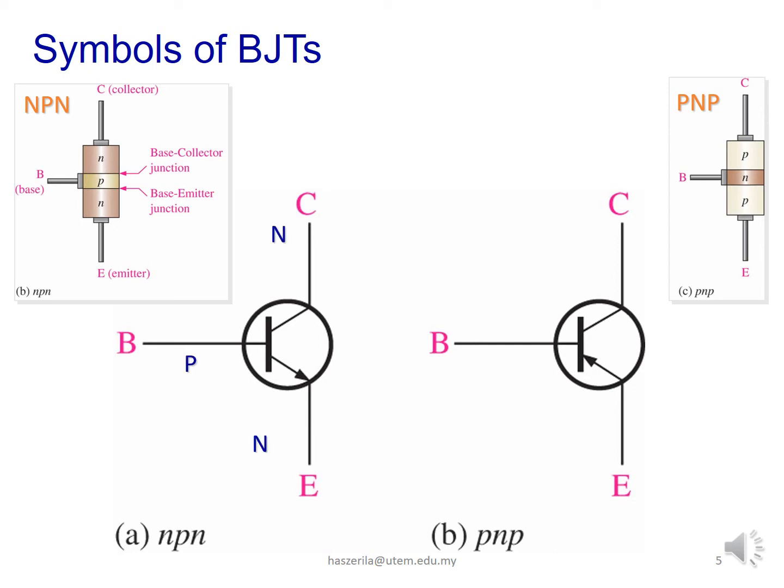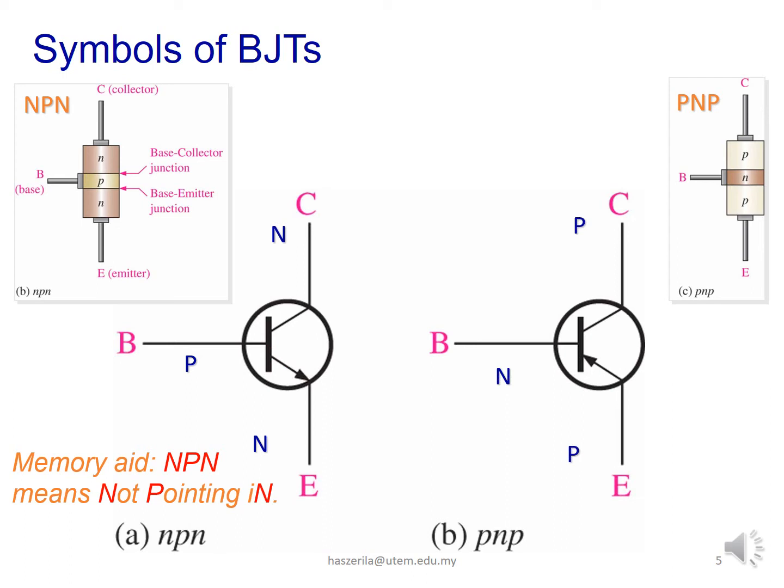The NPN transistor is called a minority carrier device because minority charge carriers at the base side are used to control the large current at the other terminals of the transistor. The current moves from the emitter to the collector, where electrons act as minority carriers at the base side. In the PNP transistor, the current direction and voltage polarity are reversed as compared to the NPN transistor.